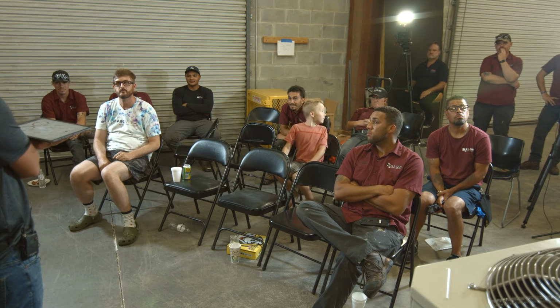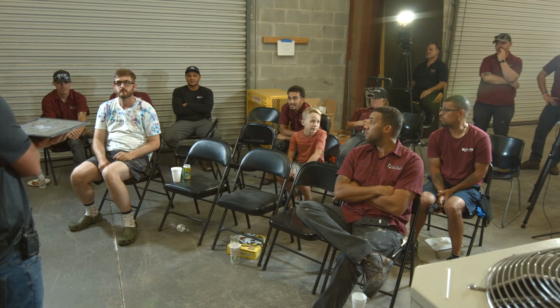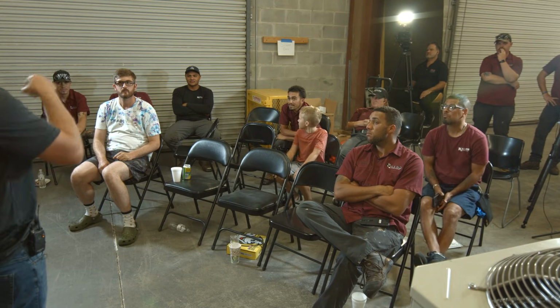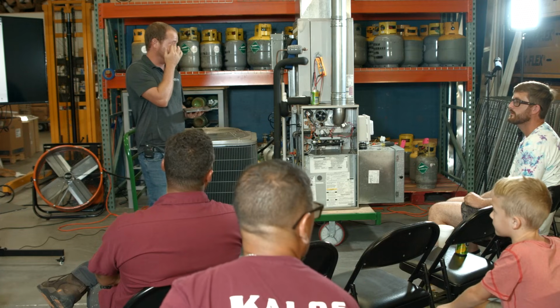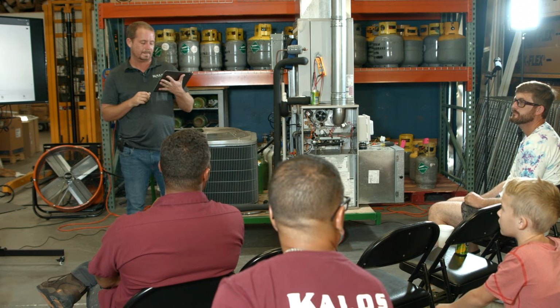The G collar. Y and G going to the blower. Yeah, but you'd have to open up the panel, that's the thing, and we have to put a jumper in too and remove it. And low voltage can still hurt you. Of course, keep the condenser on. Yep. You don't mess around with low voltage.